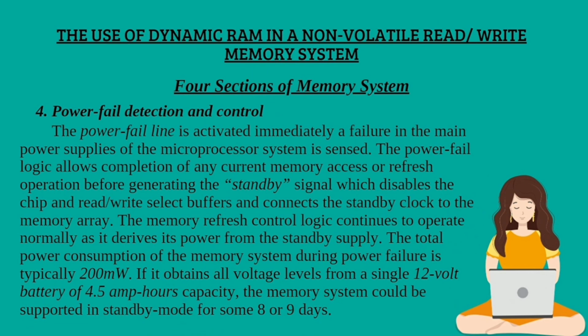The total power consumption of the memory system during power failure is typically 200 milliwatts. If it obtains all voltage levels from a single 12-volt battery of 4.5 ampere-hour capacity, the memory system could be supported in standby mode for some 8 or 9 days.